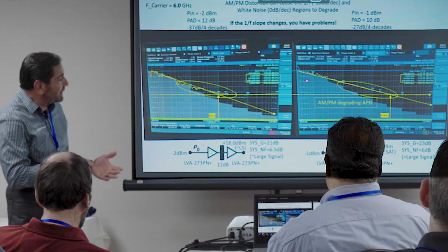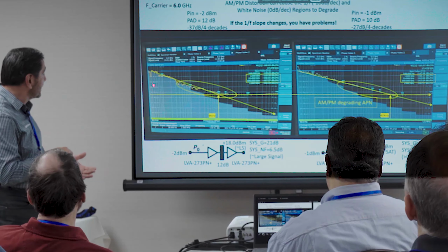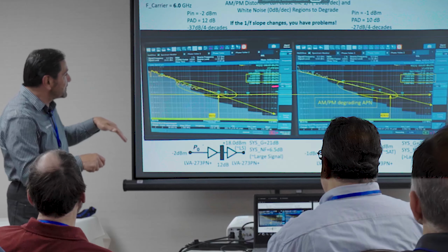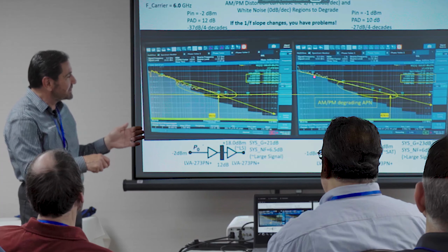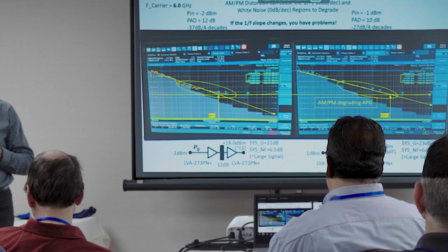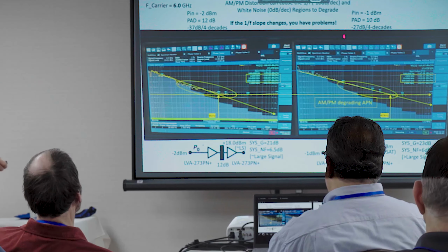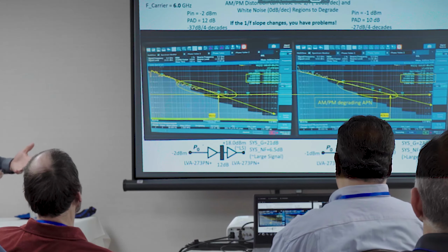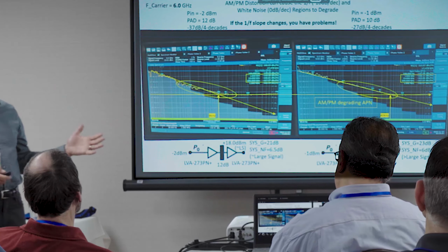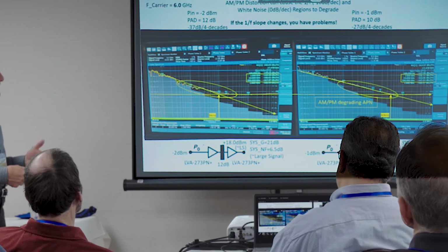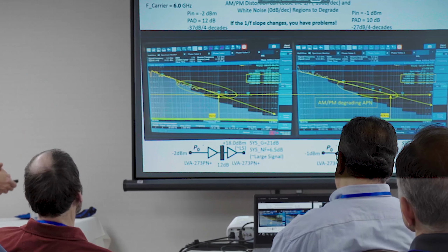And I know this 1 point here, but even look at this point, right? We about 150, yeah, it came up a little bit. Because again, we're still sitting on the noise floor here, but you would find that this may be affected as well. But my 10 dB per decade slope no longer holds, right? I'm 27 dB per 4 decades. I'm no longer 40 dB per 4 decades. So if you're a low phase noise guy, you want to know about this. Something's happening here that you're not aware of, or perhaps you are and you don't care, or perhaps you just missed it because you don't have a phase noise analyzer and this is in the noise somewhere.